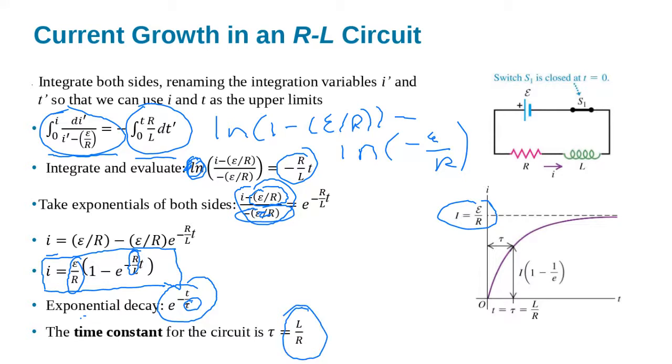So that means our time constant for our circuit, the time taken to get a change in current by a factor of e, which is how exponential decay and increase works and is described, is L over R. For a circuit with an inductor and a resistor, that time constant gets bigger for larger values of the inductor, and smaller for larger values of resistance R. So if we want a large time constant, a slow change in current, then we want a big inductor and a small resistor.